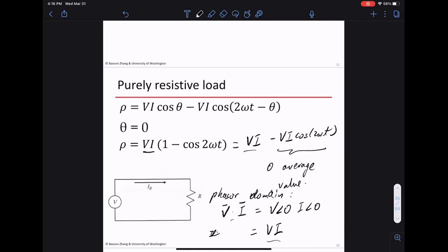Are these basically the steady state and transient state responses, or is that something different? Not exactly, because everything is in steady state. This is actually not a transient, because it's the same sine wave that just goes on forever. Rather, this is a constant value, V times I, versus something that's averaging out to be 0 across time.